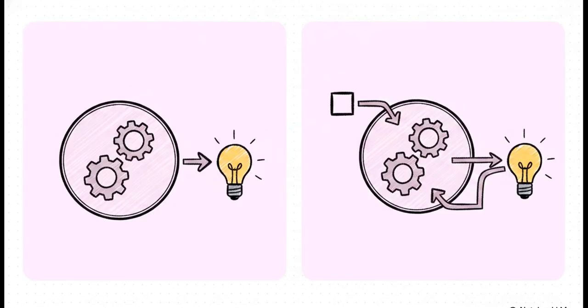And a massive structural pillar in that FSM foundation is nailing down the difference between Moore and Mealy machines. So, in a Moore FSM, the output depends purely on the current state. But in a Mealy FSM, it depends on the current state and the current inputs. Mastering these transitions and optimizing your sequence detectors on paper is exactly what prevents catastrophic logic bugs from ever making it into your final silicon.